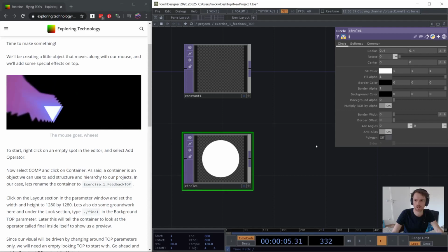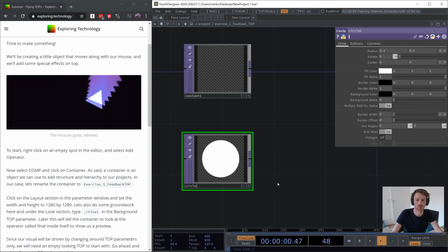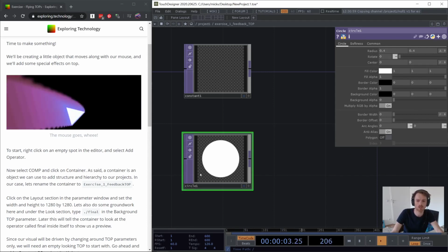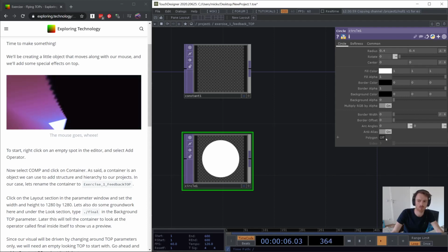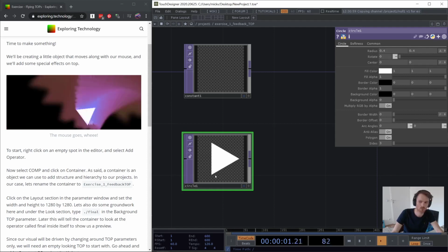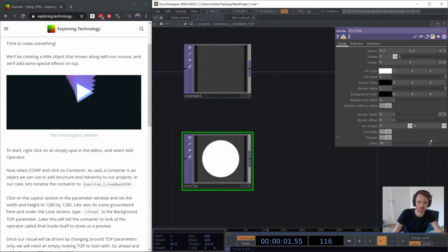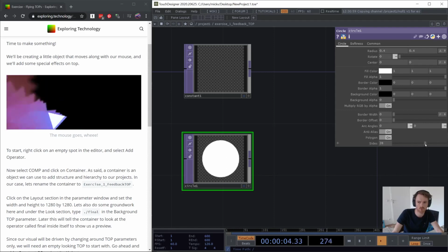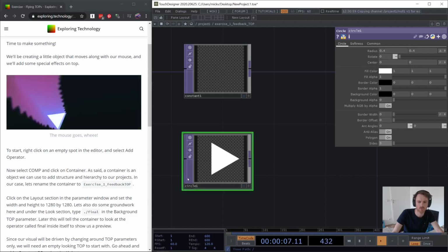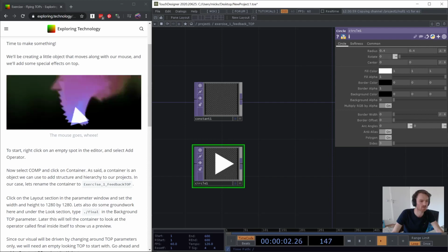This is because the circle has a lot of different options. We can completely customize something that starts out as a circle. And in our case, what we're going to be doing is toggling this bottom parameter called polygon from off to on. You'll see it instantly turns into a triangle. This is because it's currently turned into a circle with only 3 points between it. If I increase this point number by changing sides and going up, you can see that I'm slowly going from a perfect circle down towards a triangle. So triangle is the most minimal version of a circle, so to say.